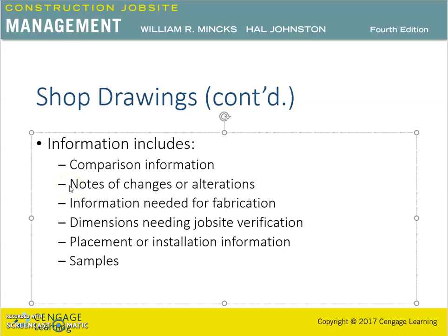Notes for changes or alterations from the construction documents are concerned with the changes or differences from the original documents, and these notes should be made on the shop drawings for the architects' and engineers' approval. Ultimately, they are responsible for changes in these drawings and should have the opportunity to analyze any modifications. A dialogue should occur between the fabricator and the architect and engineer about any areas needing clarification.